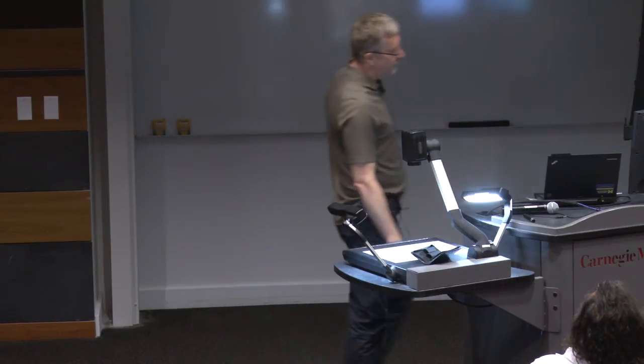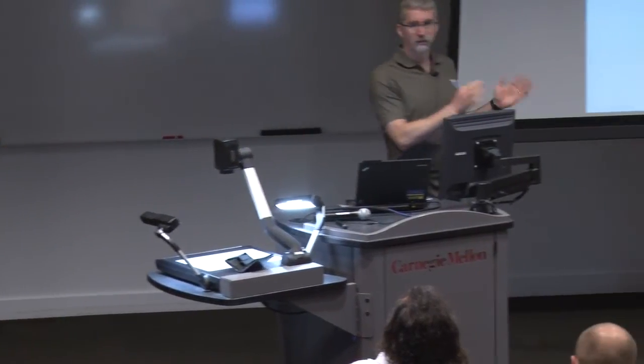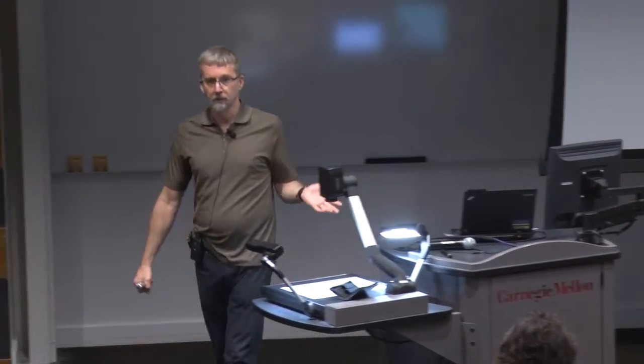Now we're going to get beyond this stable sagittal motion. That's going to happen. We are going to get it. And then we're going to start looking at lateral motion. Well, when I'm doing lateral motion, my current mechanical phase variable is doing what? It's completely out the window. And so then we have to start thinking about whether we want a library of behaviors with different mechanical phase variables associated with them, or whether we use other means of gait synchronization, like fundamentally going to time. I think that's the point, Art, where I make that decision.